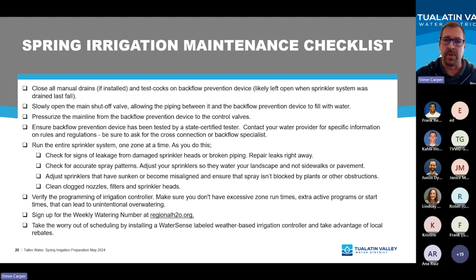Sometimes the controllers will only adjust in 5 or 10% increments. So again, you just get it as close to the number as you can, turn the dial back to run, and you're done. What that does is it recalibrates all of the zones accordingly. So for 112, you're adjusting up by 12% all of the zones on the system, and you don't have to do any calculations. In the fall, for example, you may get a number of, say, 0.89 inches. You simply think of it as a percentage, and then you're adjusting down by 11% all of the zones on your system. It makes it really simple.